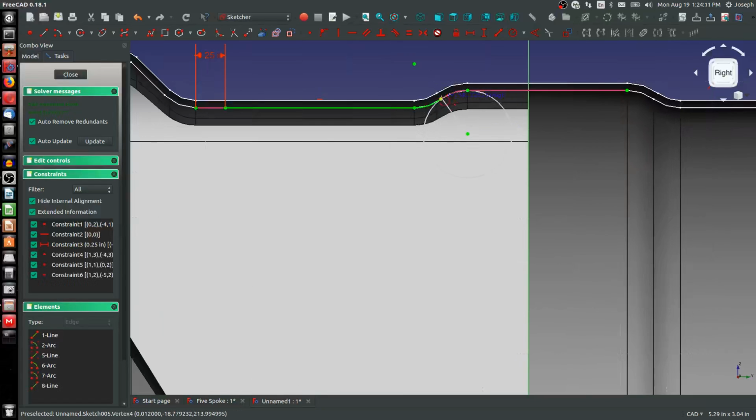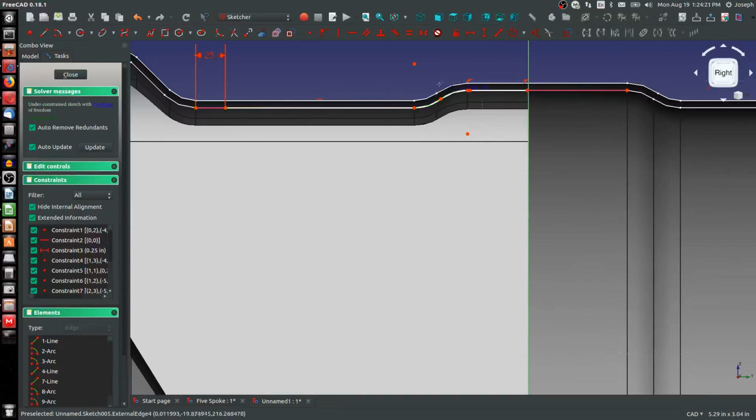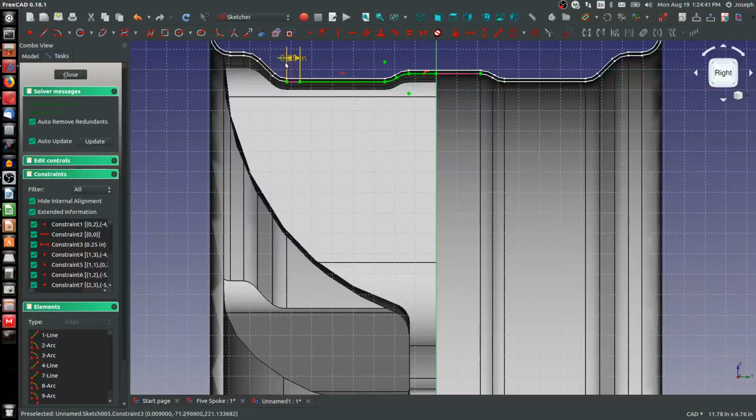Let's go to these points here. Run a straight to be coincident to this line. And I didn't snap there, so let's grab that. Okay, merge these 2 points. We've got 1 degree of freedom. It looks like this endpoint didn't become coincident like I was hoping, so there we go, fully constrained.